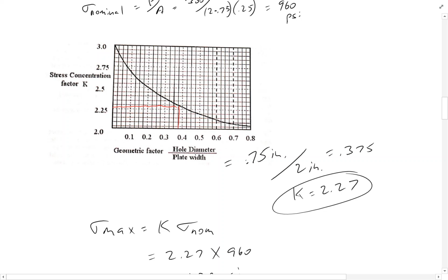Okay. I have a copy of Roark's, I'll bring it in. You can just look through it. Again, today, it's not something you're probably going to do. You're probably going to do the FEA, but it gives you some idea. It's useful from a geometrical standpoint to look through it and see what some of the worst shapes typically can be. A hole is not a terrible one, especially if it's a reasonable size hole. The smaller the hole, the worse the factor, the worse the impact.